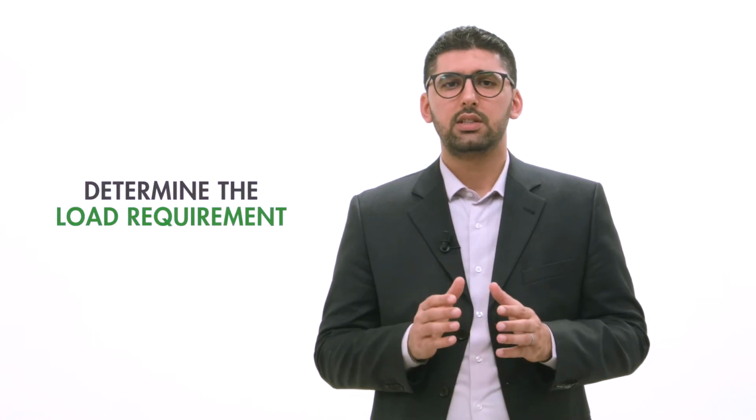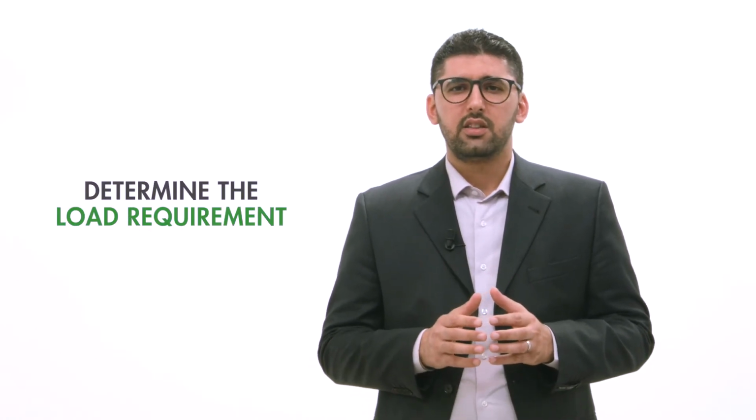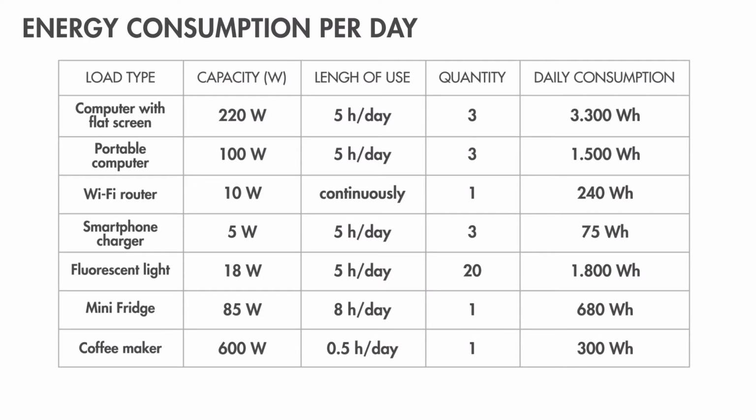The first step in installing a renewable energy system is to determine the load requirement. This table shows the load consumption of the office in kilowatt hour per day. As we can see, we have the load type, the quantity, and the number of working hours for each load per day. By adding all load consumption, we get the total load consumption per day, which is around 8 kilowatt hour.